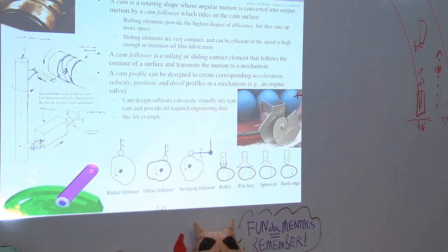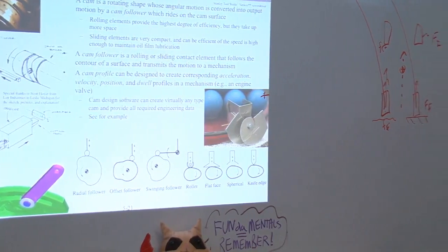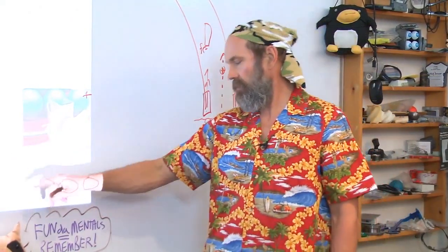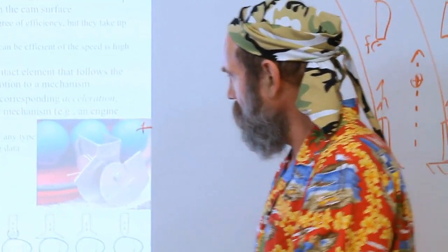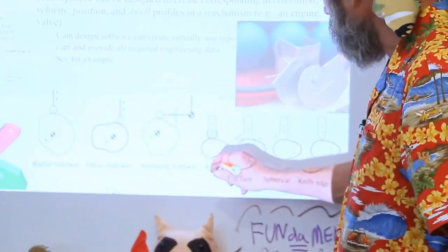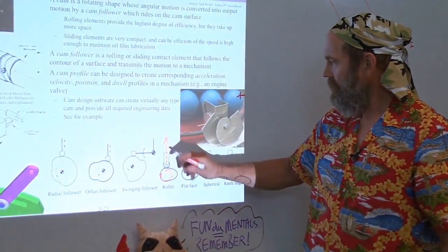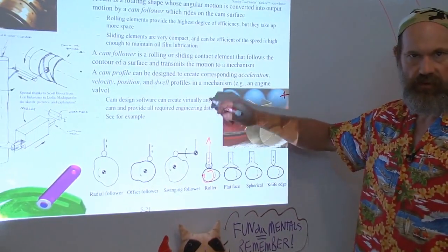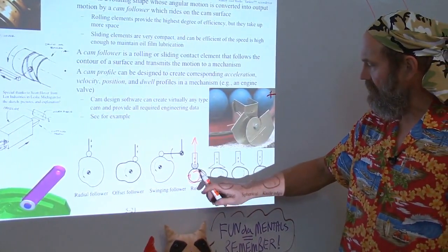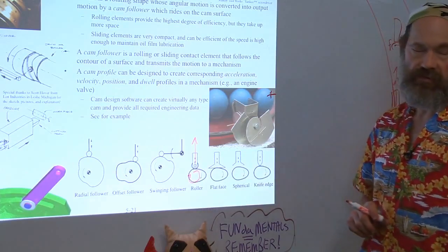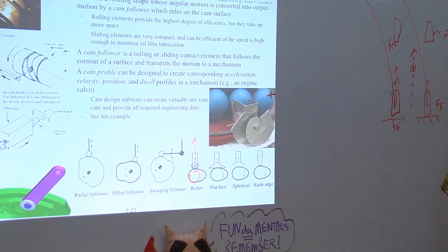Okay. When you go to design a cam, and there are cam design packages, or often you'll write your own software, the critical elements become, how do I relate rotary motion that would be continuous to the linear motion, which now has some profile based on the shape of the cam and the constant input rotation on the camshaft itself.